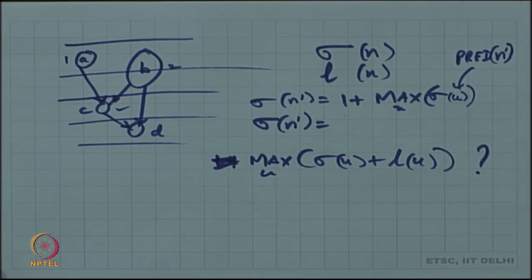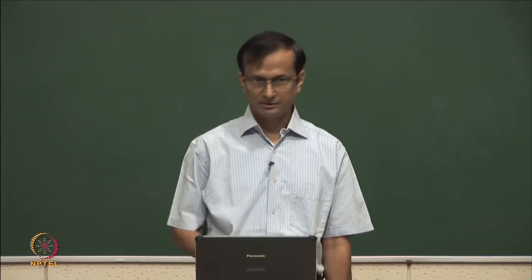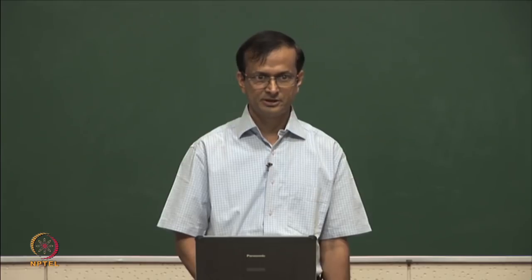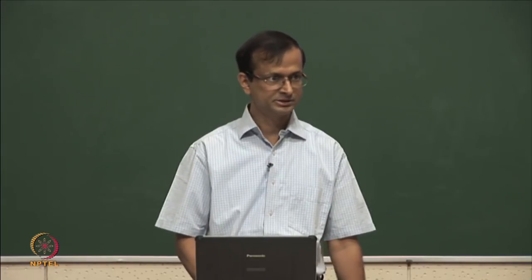Here u is over all the predecessors of the node. So it's a simple computation. This is still optimal. The ASAP schedule is still guaranteed to be optimal. The ALAP schedule similarly you can obtain. Now let's say my scheduler was considering height in its algorithm. Then height will now be computed in terms of cycles. That's an easy computation, but it would be in terms of cycles, which is the sum over all the individual cycles of multi-cycle operations, if there are any.